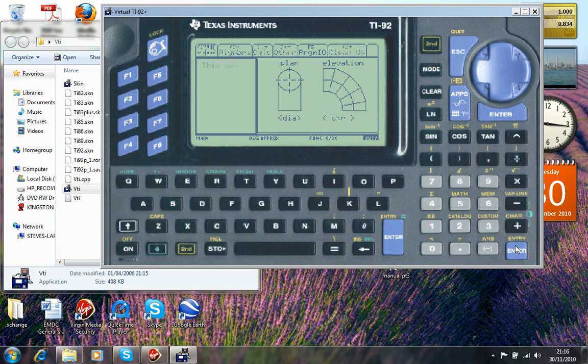And again press enter. This bend requires minimum 7 segments plus start and finisher. Start and finisher equals 1 segment, so that's 8 in total. This isn't set in stone, but it's a good guide. So I'm going to go for 8 and enter again.